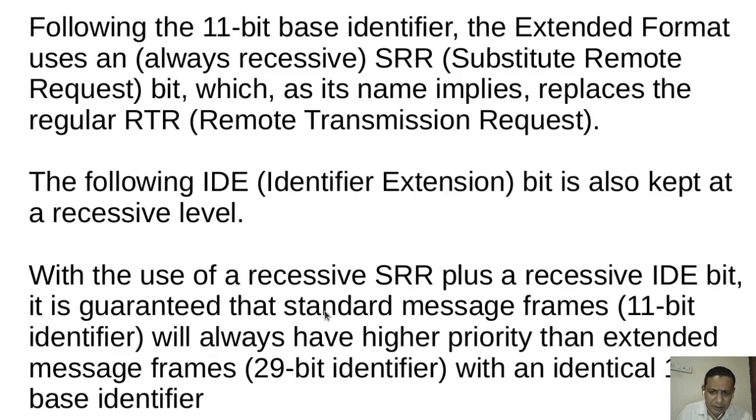It is guaranteed that the 11-bit standard message format will have higher priority than the extended format. That is, compared to the standard frame format, the extended format will have lower priority. So normally the standard frame format will dominate compared to the extended frame format.